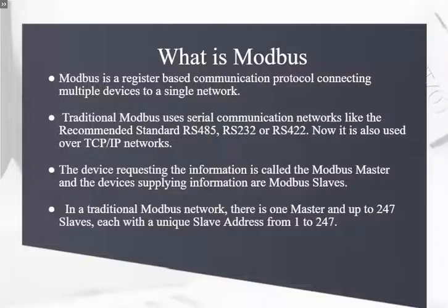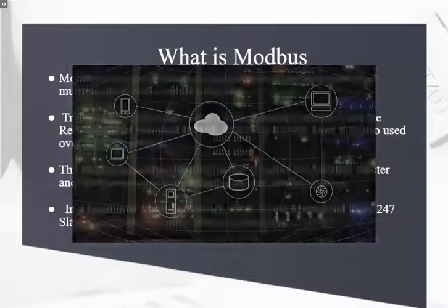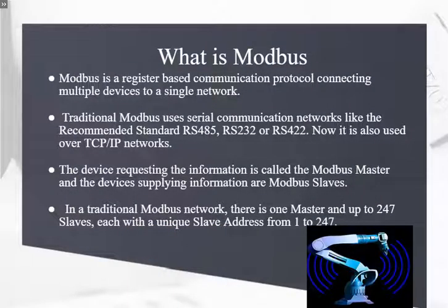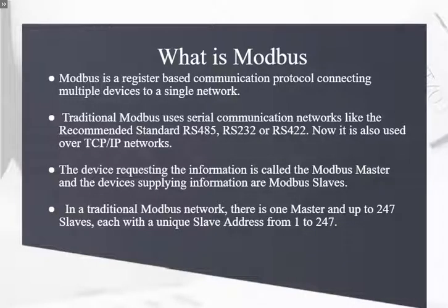The Modbus Protocol provides a standard that the controllers use for exchanging messages, like a computer language, and it uses a client-server type protocol. The controller requesting the information is referred to as the client. The device supplying the information is referred to as the server.